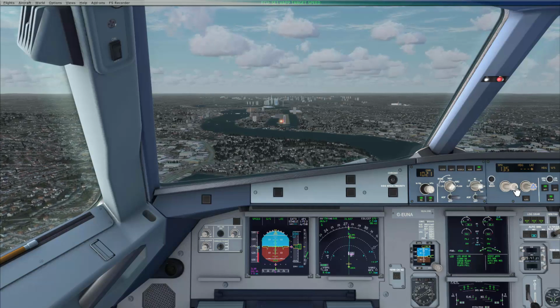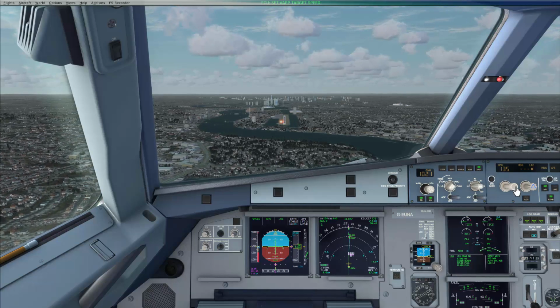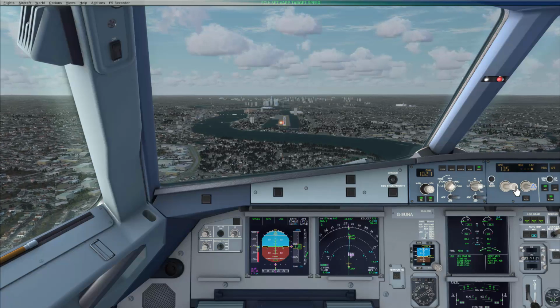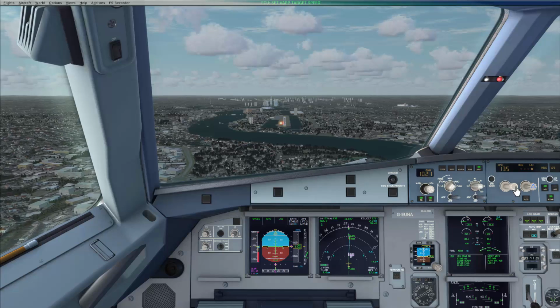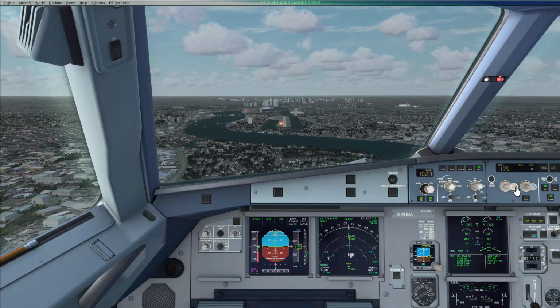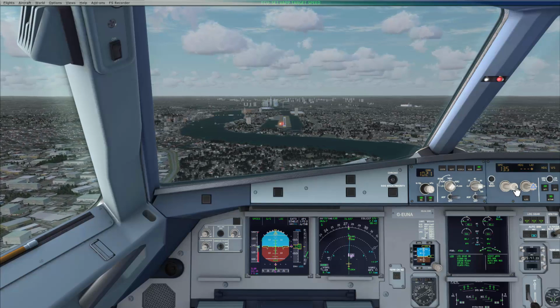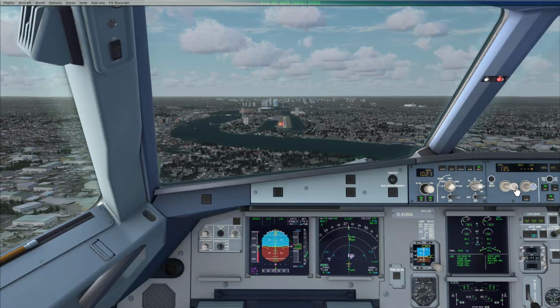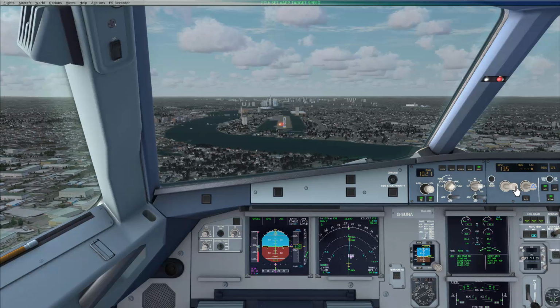taking off the throttle at the appropriate point and flaring, which happens considerably earlier because we're coming down at a much steeper angle. We'll get calls starting at about 130 feet, advising us on when to retard the throttle and flare the aircraft.